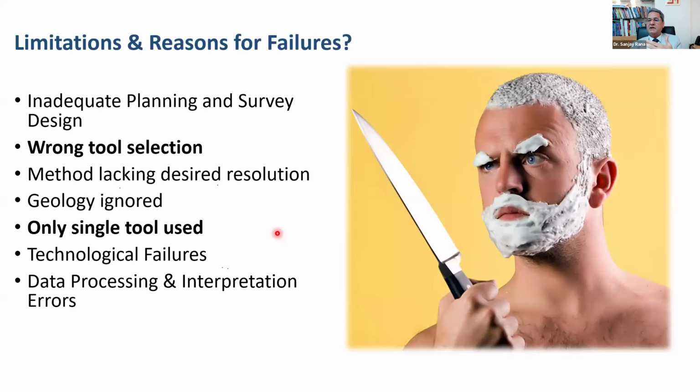X-ray from which angle is to be done, a practitioner has to decide that. So inadequate planning and survey design, wrong tool selection, method lacking desired resolution, geology ignored, only single tool used. One of the biggest problems. Don't try to save money on geophysics. Always use a combination of tools. Then only you will get a unique solution.